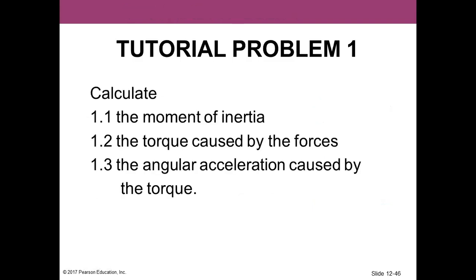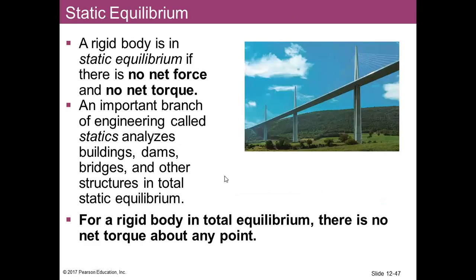So now you need to calculate the moment of inertia. Then you need to calculate the torque caused by the forces. Then you calculate the angular acceleration caused by the torque.